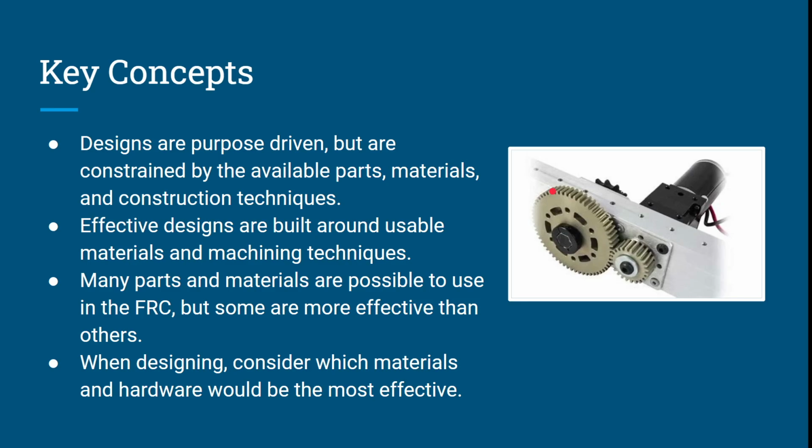How would you make this piece of VersaFrame? Let's say it ships 20 inches long, and you want to make it 8 inches long and drill a hole through it. So you're going to make a mark at 8 inches from the edge, and then you're going to use that to cut it, either using a radial arm saw or a bandsaw or a portaband or a jigsaw or a table saw maybe, or a chop saw, something like that. Whatever tool you have available in order to cut it to the right length.